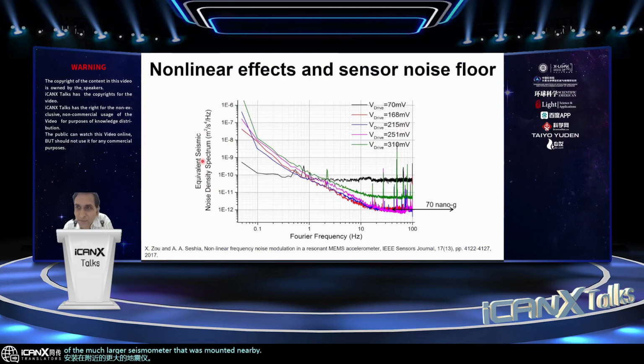And Shudong also did some very nice work around looking at the impact of nonlinearity that is inherent in these sorts of MEMS devices. So as many practitioners in the field will know, as you scale down the dimensions, you operate under vacuum conditions. High Q responses often imply that your devices can go nonlinear at very low drive levels. And in this work, Shudong looked at the impact of that on noise folding to the carrier.